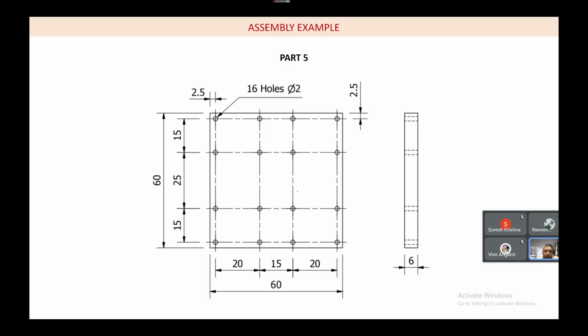This is going to be on the base plane. 60 by 60 square. Finish sketch. So I'm going to extrude it up to 6 above.